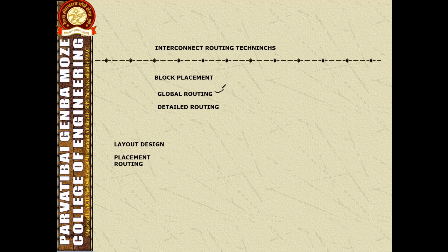In order to select the global routing, the best detailed routing for all the channels and switch boxes is selected. However, estimating the exact result using the detailed routing is a challenging task. Although the density gives good utilization without routing the channels, the main goal here is to assign the wire.